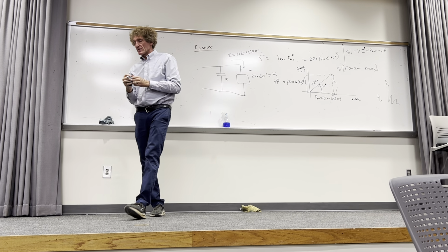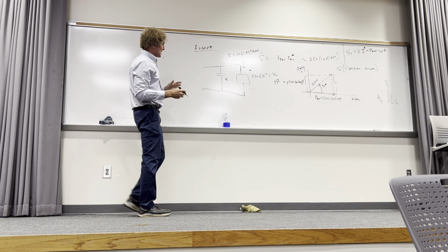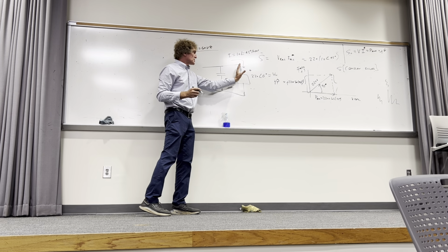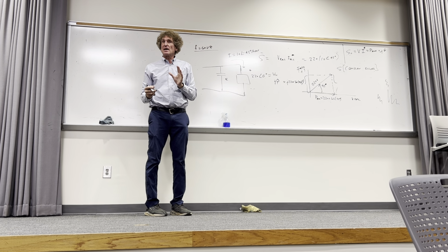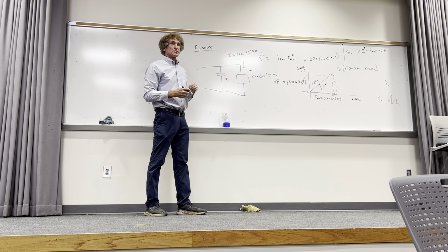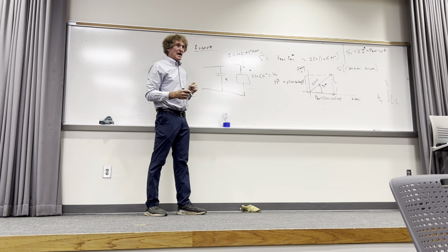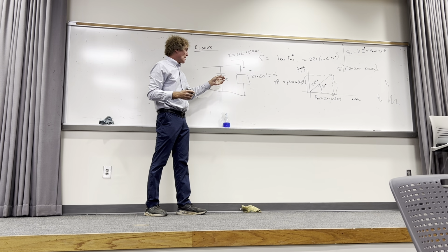And here's something I have to tell you. Whenever you talk about powers, everybody sees these two loads, this load and this capacitor, are in parallel. You all follow me on this one, class? So the total complex power associated with the load and the capacitor in parallel with it is just the complex power at that load plus the complex power here. Everybody with me on this?